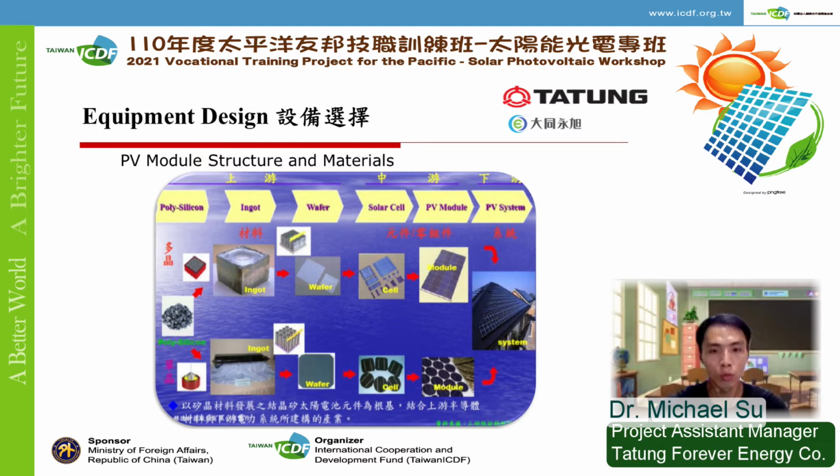No matter if it's mono or polysilicon, we will build them into silicon ingots. It's kind of like compressing them into a brick. They are all made from silicon materials. Then we will slice them into wafers. Now, the difference between mono and polysilicon is that polysilicon can be made into a complete square, but not monosilicon. So if you look at the picture, you can see that the four corners of the monosilicon are a bit of a curve. So you can easily determine if your module is using a monosilicon solar cell or a polysilicon solar cell by looking at the panels.